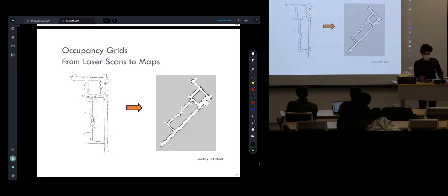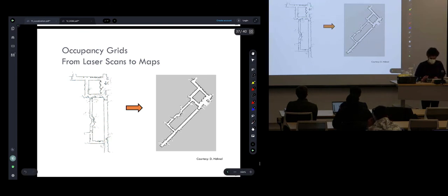Somehow. Although there is a way to run particle filter as you build the map, and that's called FastSLAM, and it's known as the G-mapping package that you see in ROS. That's what it's doing. It builds the map and runs the particle filter in the map as you build it. It works well. It's a very nice work, but it has a scalability problem because you can't use so many particles, because each particle is tracking its own occupancy grid map. It's going to be very expensive if you use a lot of particles. But it is a very successful and useful package.